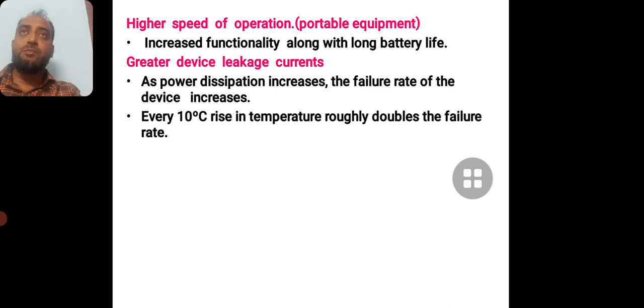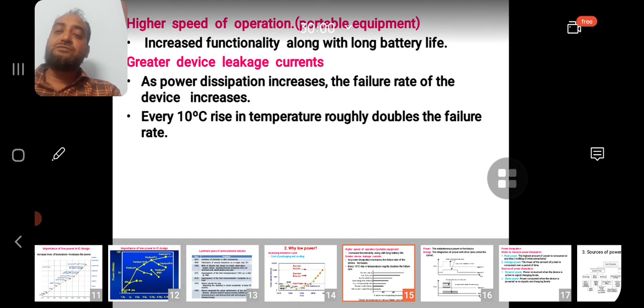If low power design is not properly developed, the power consumption of the chips will increase, and as the power consumption increases, the ambient temperature of the chip will increase, which leads to a greater failure rate. So it is very important for design engineers to have low power designs.